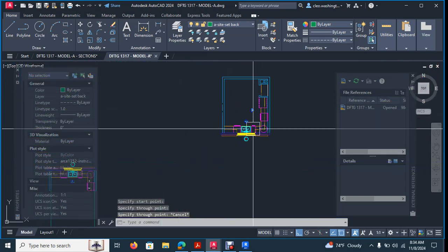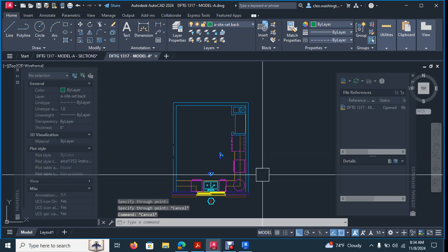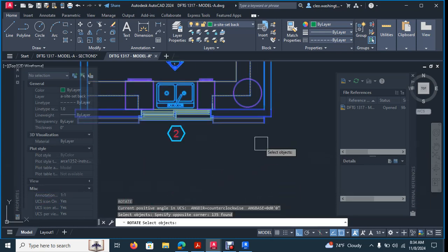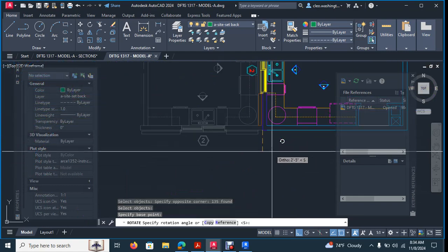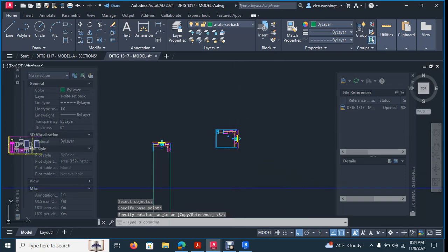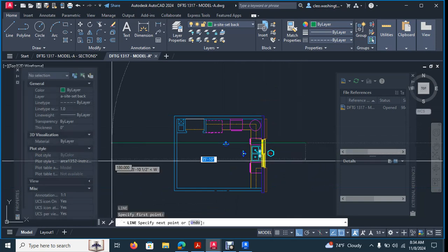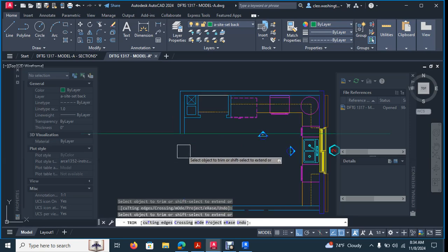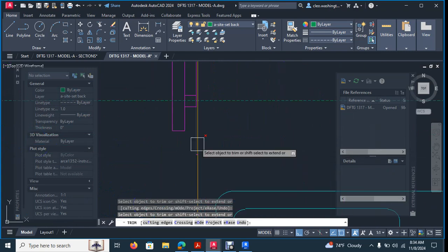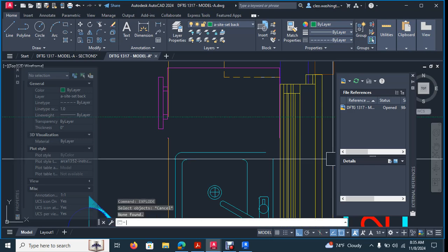All right, now let's get this interior elevation set up for drawing. So now we can rotate this one, RO. Select it. Let's grab this corner, the bottom right corner, and let's rotate it twice, just like that. And let's draw a divider line here. Let's trim it here, here, here. Let's trim all of this. Explode the window, even though the window is not pertinent.